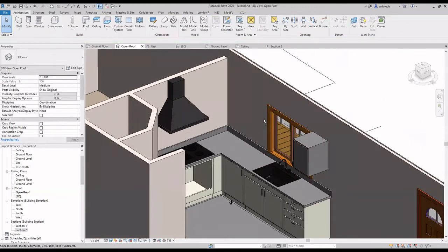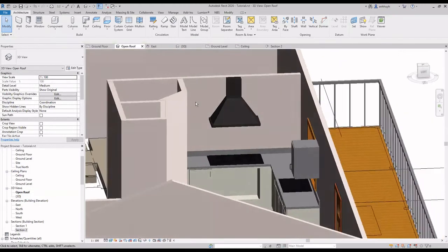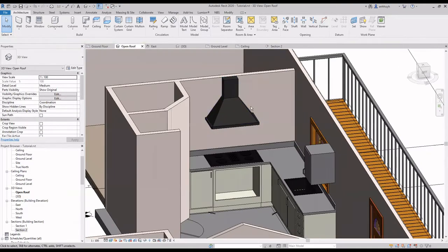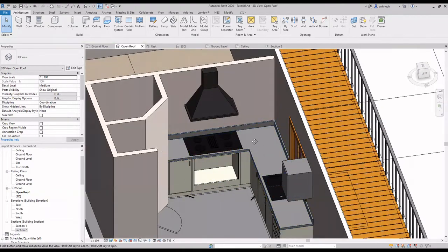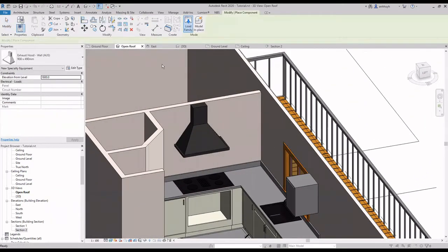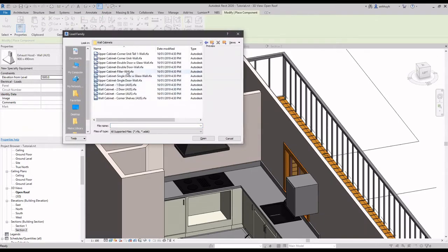And for your design, you'll need to add upper cabinets on the sides, filling up these, okay? Just according to your floor plan. So follow the floor plan. For the corner, similarly with the base cabinets, you can use filler walls and make sure that they overlap so that there's no gap.